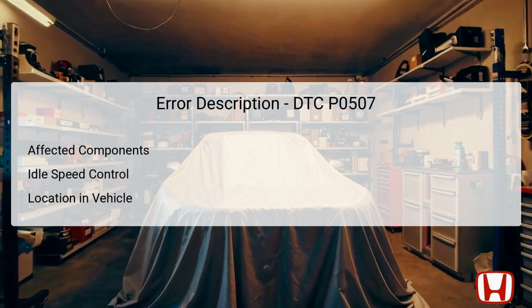DTC P0507 involves a malfunction in the idle speed control system, specifically linked to several key components. The primary affected components include the throttle body, throttle actuator, and various sensors like the APP and TP sensors, which are critical in measuring the throttle position and engine load.